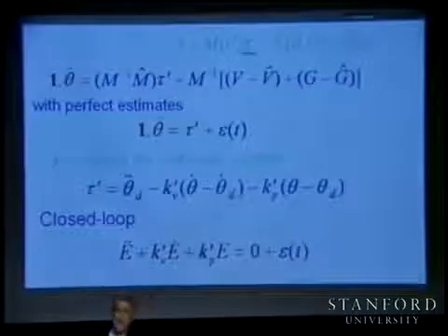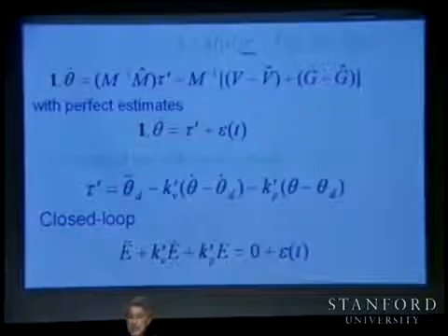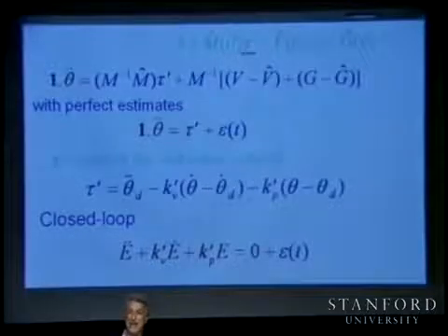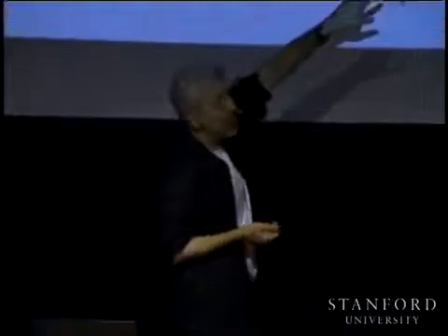And if that estimate is a little wrong, you are changing your gains up or down. So it is sort of like a gain that you will have. If you make a mistake in the estimate of m hat, as long as m hat is positive definite from your structure, the effect of it is just scaling up and down your gains. It's not going to affect the stability too much as long as you have a positive definite matrix.